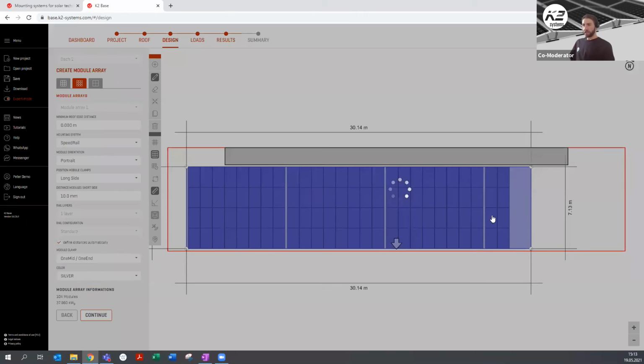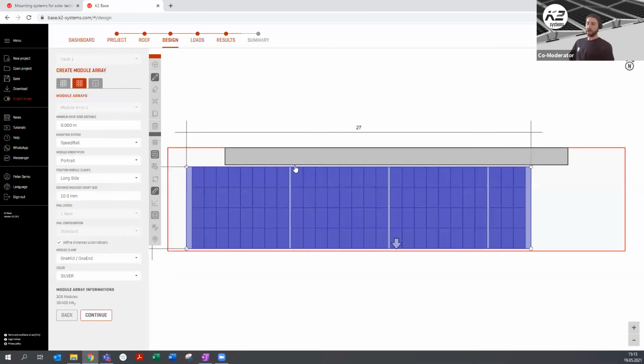What's quite sophisticated here is the thermal extension, the thermal gaps after the 8 modules, which Karen was mentioning before. 8.8 meters is the longest array you can get. After that, we need a thermal extension. Sometimes, depending on the module size, we only have 7 modules by now because the module width is getting bigger and bigger. That's why you cannot go with 8 modules as a preset. It's about the 8.8 meters.